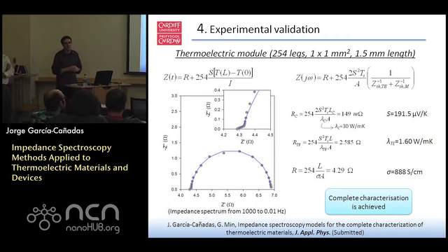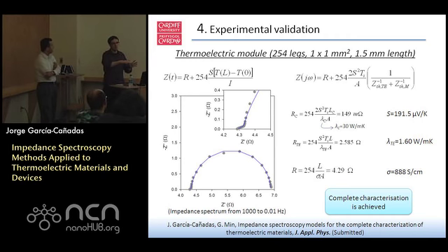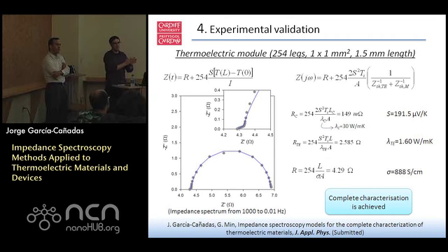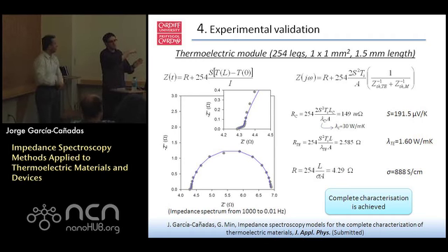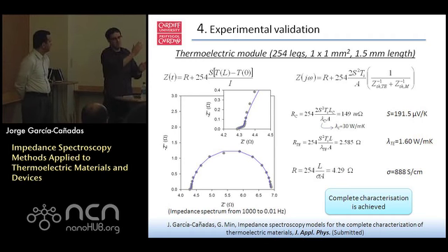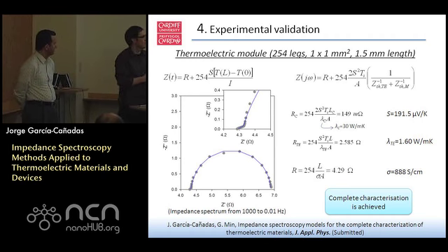Yeah. For example, in solar cells, you have your IV curve, which is nearly a diode. So usually to characterize solar cells, you fix a voltage, it doesn't matter at which point of the curve, and then you oscillate around this voltage. And you identify different spectrum shapes at all different voltages. So it's possible to look at any operating condition.